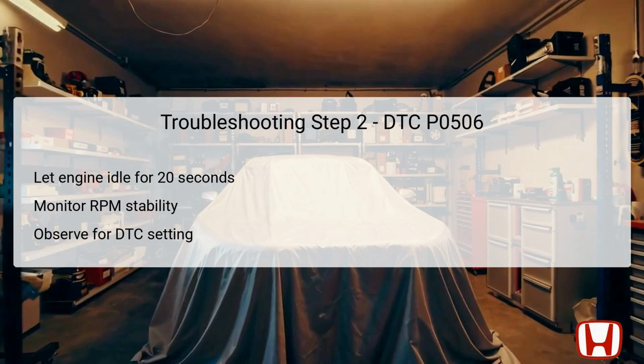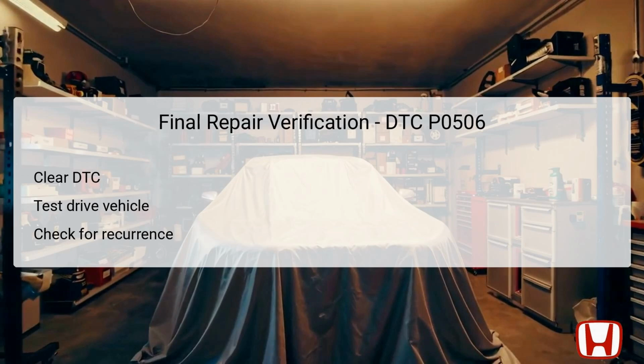The PCM continually adjusts idle speed based on sensor inputs to achieve optimal performance. If the actual idle speed is lower than the target by 100 RPM for at least 20 seconds, the PCM will register this condition and store the DTC. It is imperative to note the engine's behavior during this phase, as any fluctuations can provide valuable insight into potential underlying issues.